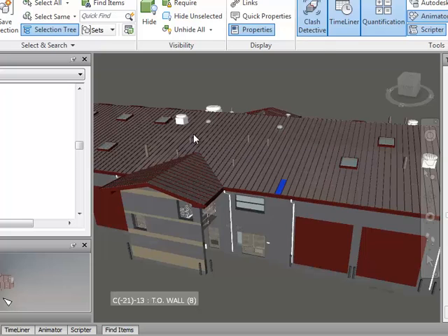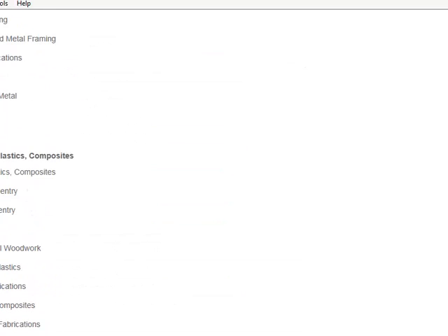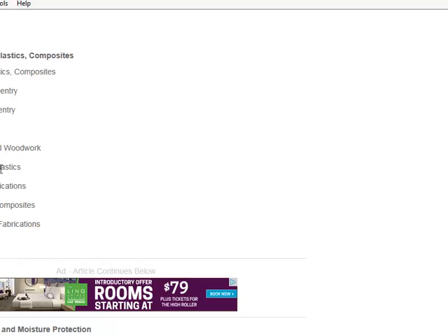So what division is cabinets in? Which division number? 13? 15? It's not 7. Division 6. 6200 is finished carpentry, 64 is architectural woodwork. What about the cabinet you buy from Office Depot? That is also considered cabinet. Yeah, that would be cabinet.